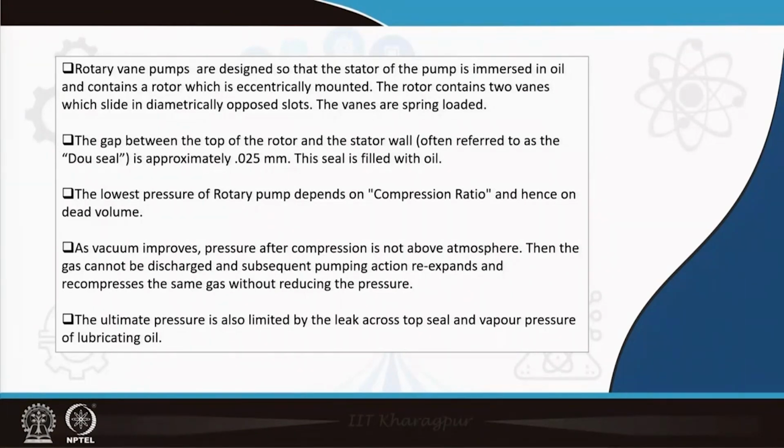Normal compressors only have 20 compression ratio, but lot of heating effects will be there. That is why in isothermal compression, a Carnot cycle or anything, if you want to make an ideal thing, you have to have aftercoolers, intercoolers. Here we do not do that, excepting the crankcase oil which is cooled by natural convection, etc., which is acting like a coolant. We are not bothered about heat much. Of course, it is better to keep it in an AC room. It is better to connect the seal, whatever is the crankcase, with a little bit of fins, extended areas, etc.